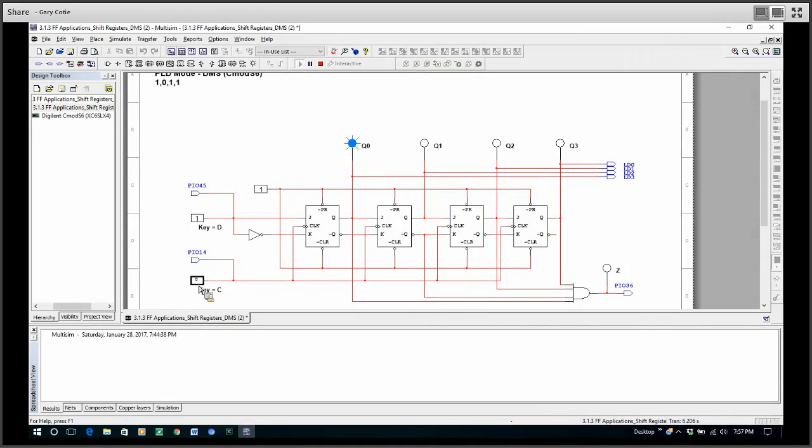Then we're going to clock it again. So we go to 1. Now the second data bit is coming in. So now we collect two of these in. And now to make the pattern, I have to make the data a 0. And now I can change the clock. And then the last one is a 1. And there we go. My circuit works.